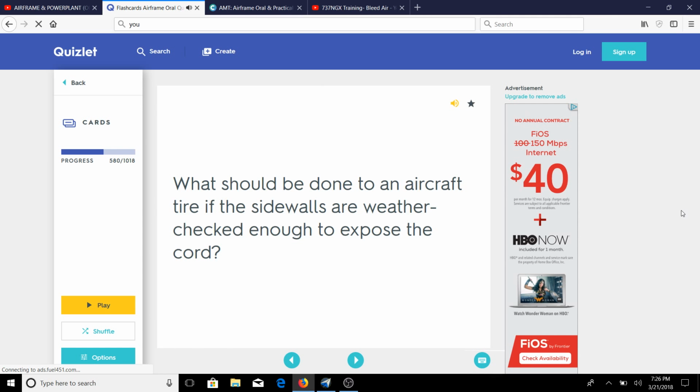Why do airplanes with bleed air anti-icing of the wing leading edge have an anti-ice overheat light? To indicate an over-temperature condition, usually as a result of a break in the bleed air ducts. What warning may be required when a nickel-cadmium battery is installed in an aircraft? A battery temperature monitoring system. At what time would a check of a landing gear warning system normally be made? During a landing gear retraction test.